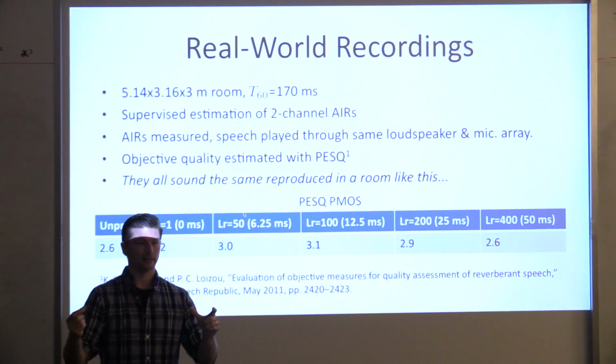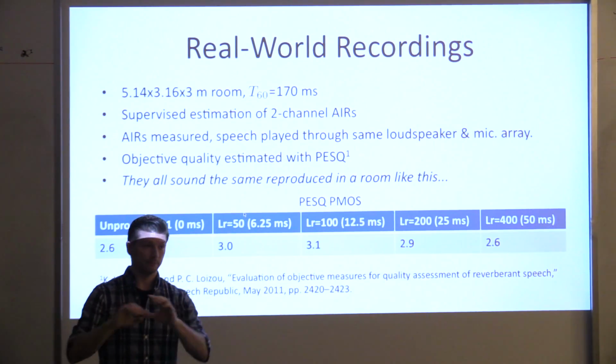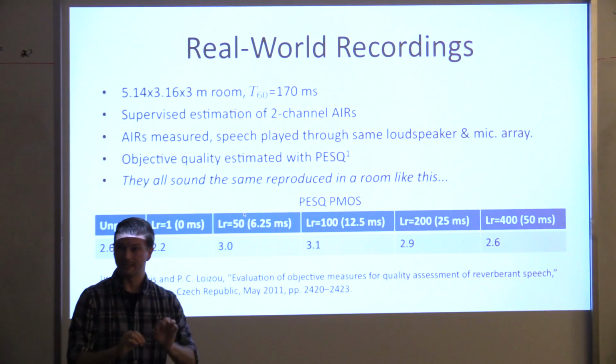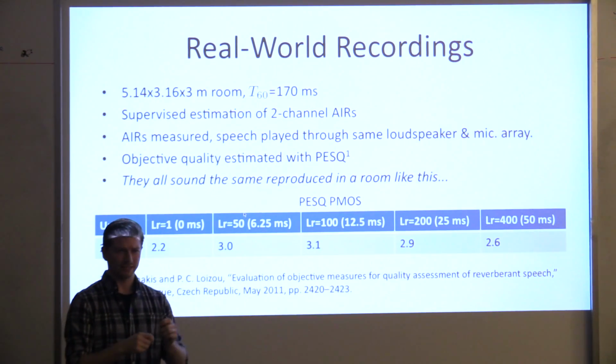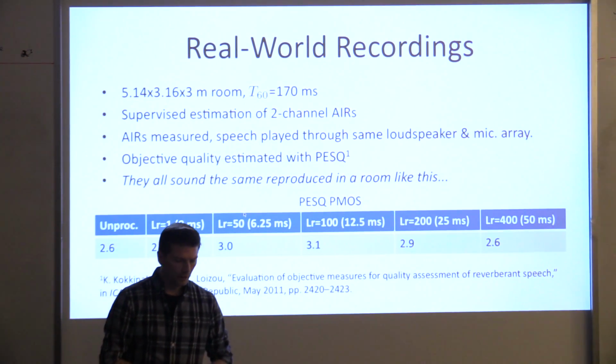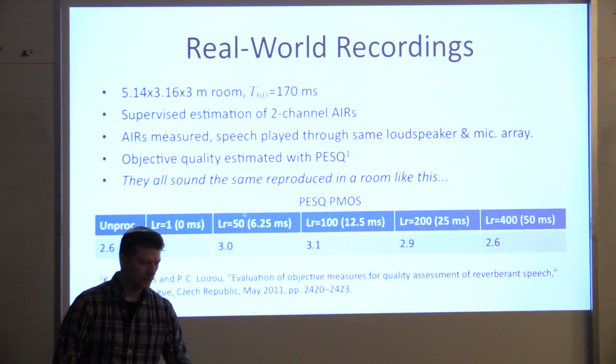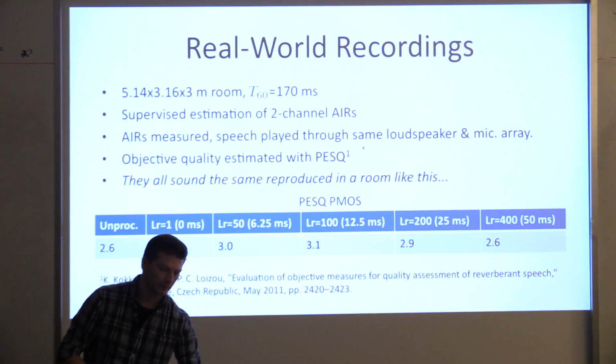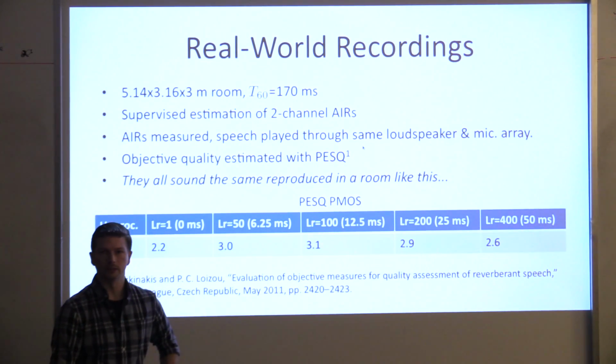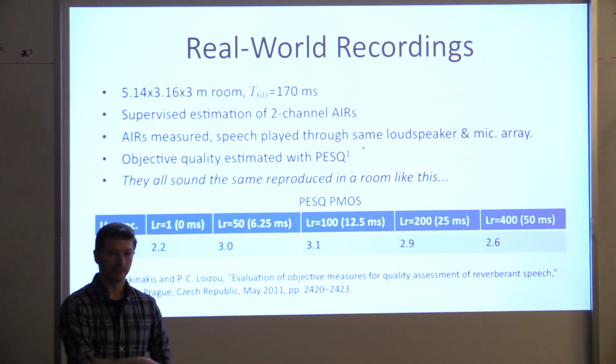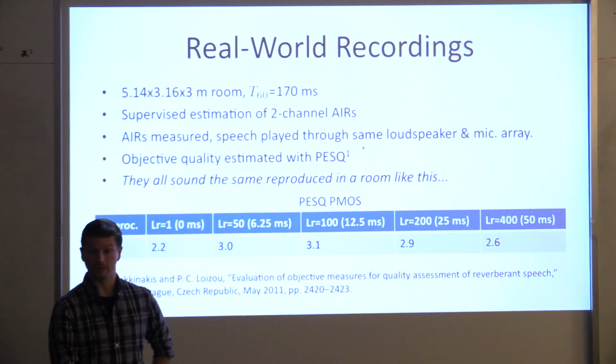And immediately after that, I played back some speech through the same loudspeaker. So I didn't move any furniture, it was almost at exactly the same time. So this is presenting pretty much the most ideal real-world scenario that I could ever get. And then using an objective quality measure of PESQ. So PESQ is an objective measure of speech quality that was originally designed for estimating the subjective score that you would get if you were listening to coded speech. But there is some literature out there that suggests that it's also a fairly good estimator of how reverberation sounds.